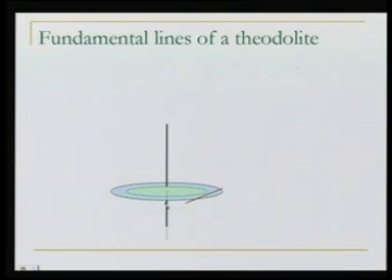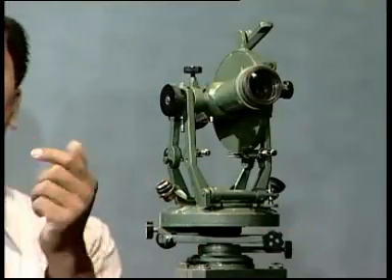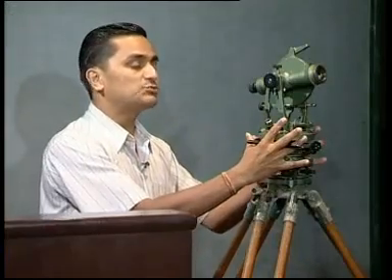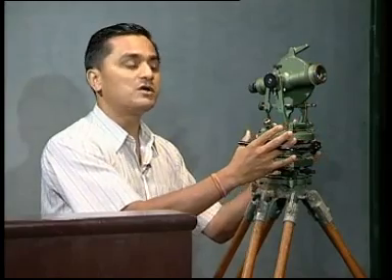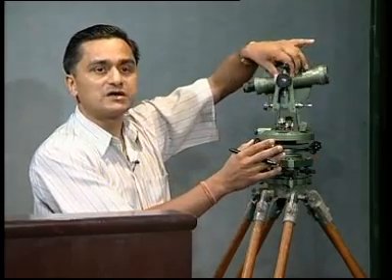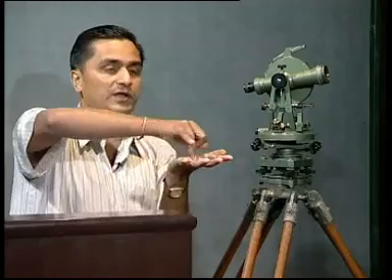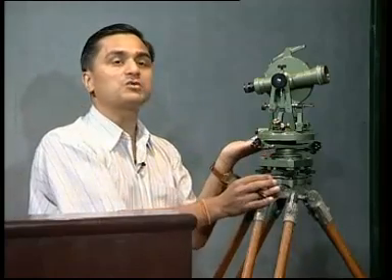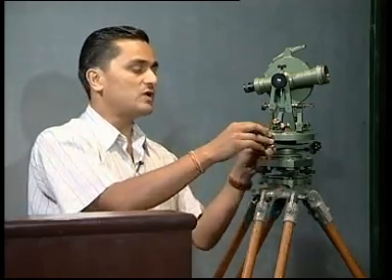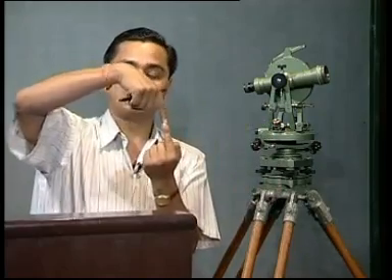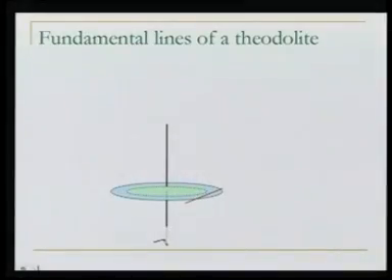Then further, we have now two axis systems in this part of the instrument. One is for the upper circle or the vernier frame and the other one is for the bottom plate. Now these two axes again should coincide, as you can see here by the dotted lines. That's for the inner one and that's for the outer one. So these two should coincide.